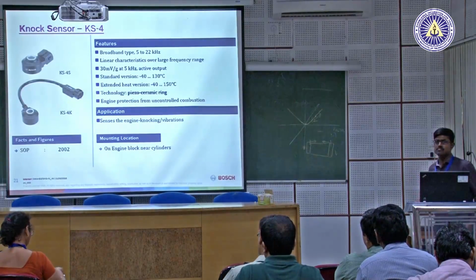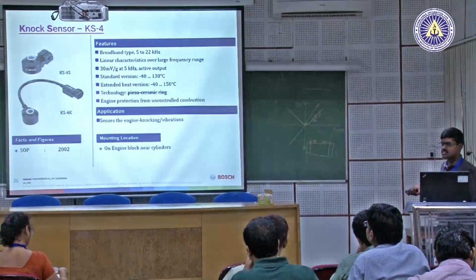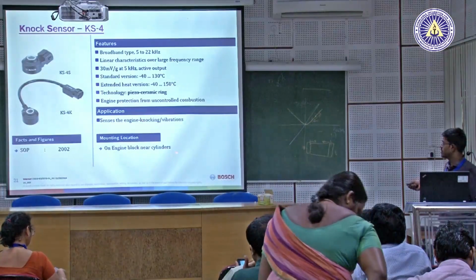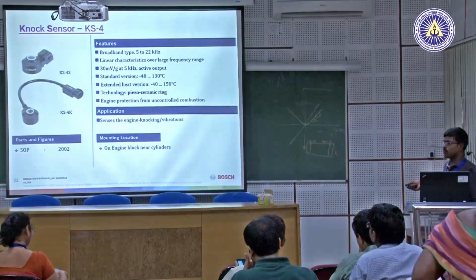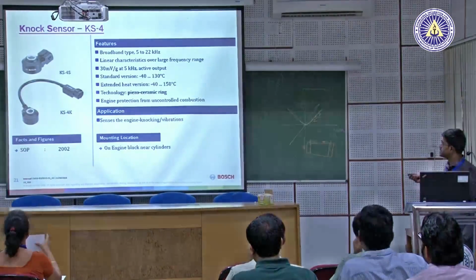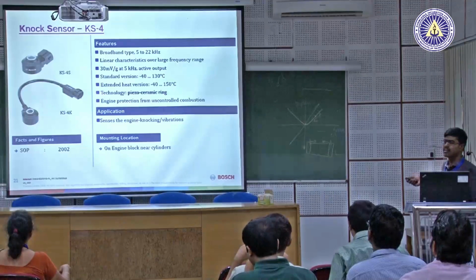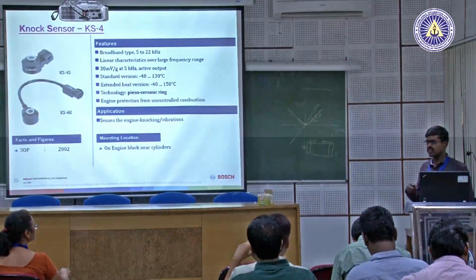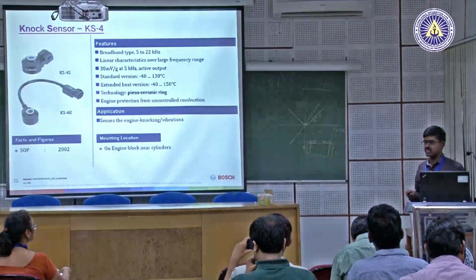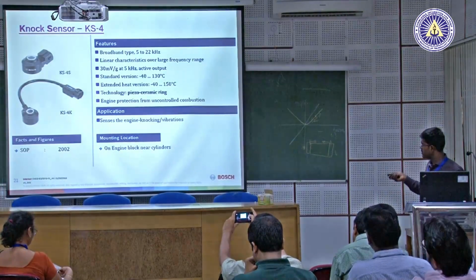So, next comes the knock sensor, which is mainly used in gasoline engines. It senses engine knocking or vibrations, and is mounted on the engine block near the cylinders. The technology is a piezo ceramic ring. The piezoelectric concept which we talked about in the earlier presentation is the same concept being used here.